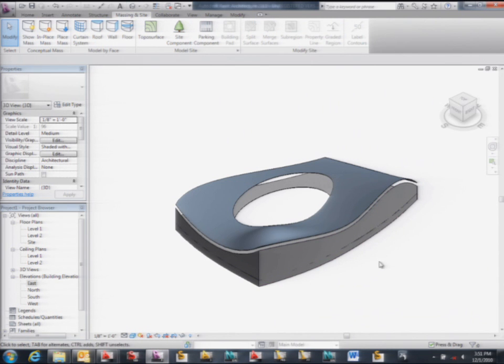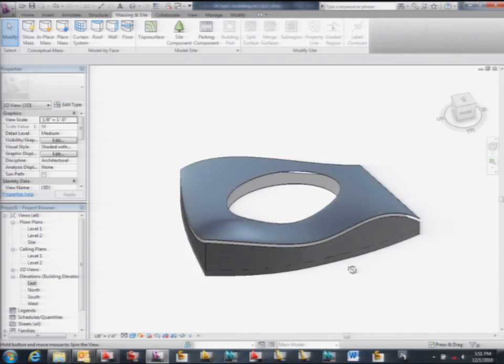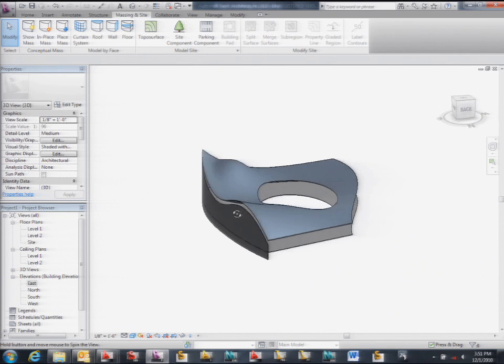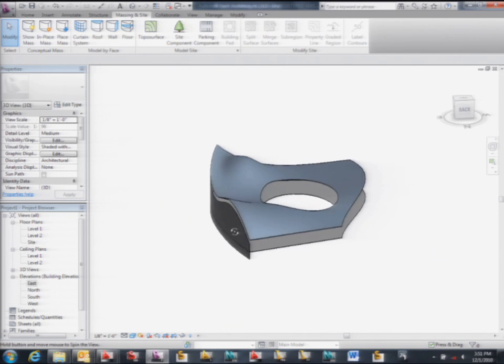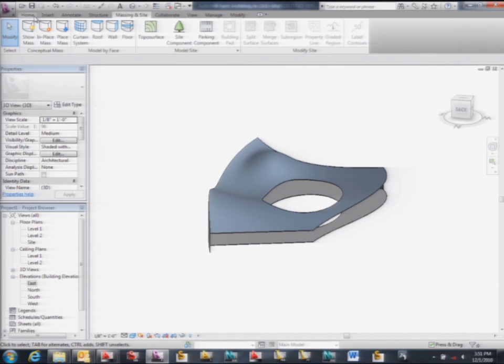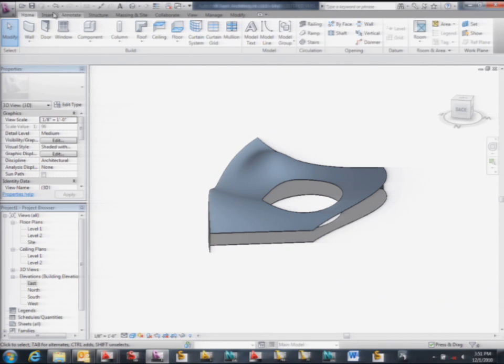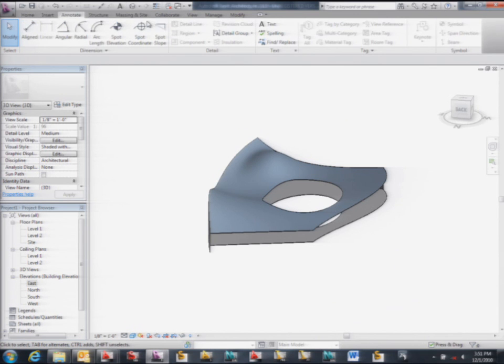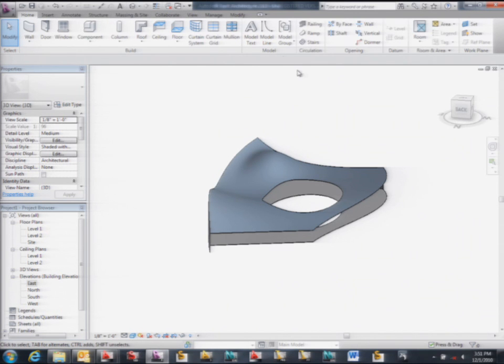So there you go. What you see here is what I get. I didn't finish everything, of course, but I have my floor, I have my roof, I have some of the walls. I could create, for example, a schedule of this, so I can get the area of this floor. And based on any changes here, because I decide that this is too big or too small, I can go back to AutoCAD, change the surface, resculpt, resave, and update here. So you are not losing data.